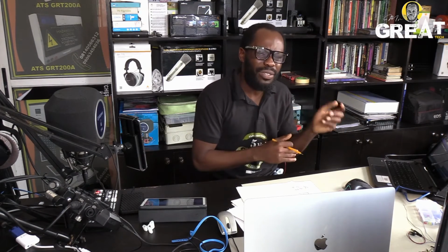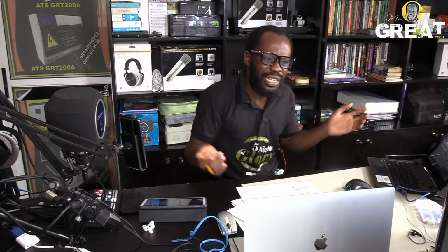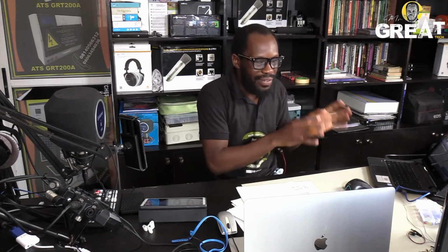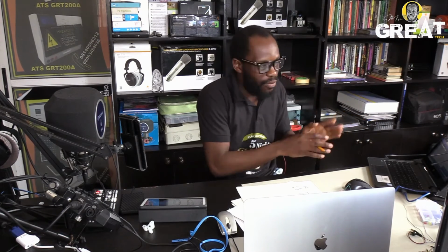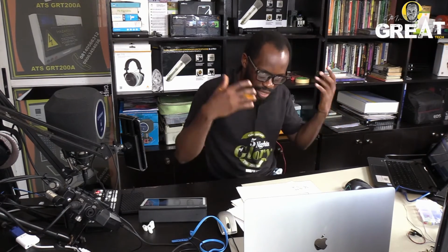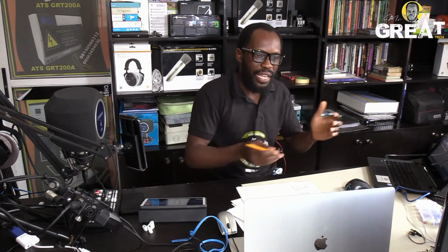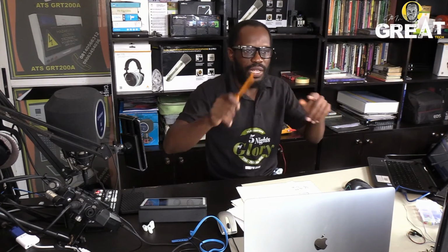Like I told you, you may say, why should they do it that way? Why shouldn't they leave it at 5 volts and stop the confusion? I'm not the one that produced Arduino. I'm not the one that wrote the programs. The way the people that designed the program designed it, that's what we are following. If you just have that mentality and understanding, you will flow. So it's the same thing. If I tell you that 0 is 0 and 5 volts is 1023, a scale of 1023.